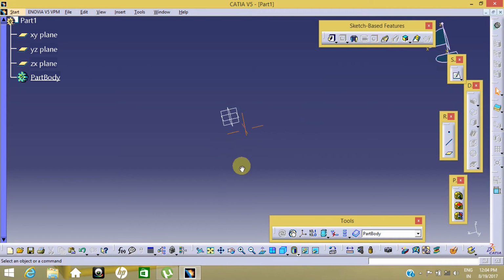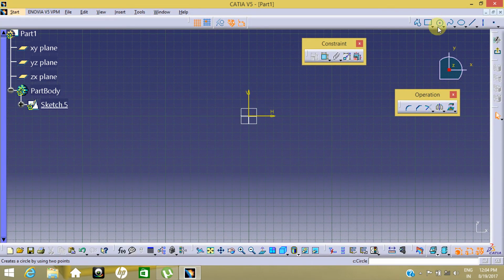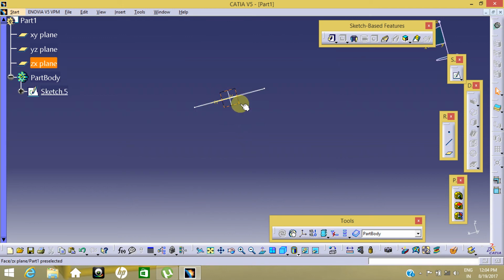Our path is lying inside our profile. So now click on the rib command that is used to move our profile along the center curve that is here and make it OK. So you will see a product has been generated like this.